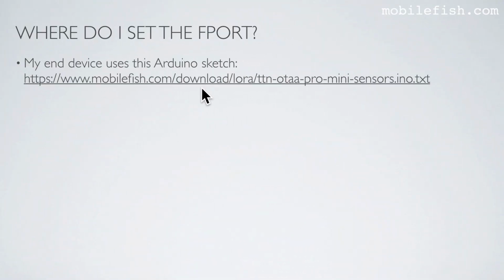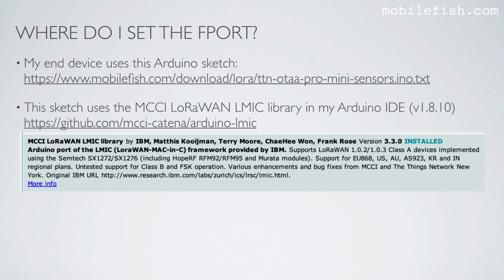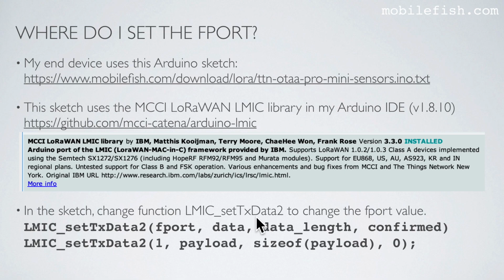My end device uses this Arduino sketch. This sketch uses the MCCI LoRaWAN LMIC library in my Arduino IDE version 1.8.10. The library can be found at this location. In the sketch, change this function to change the FPort value. In this example, I have changed the FPort value to 1.